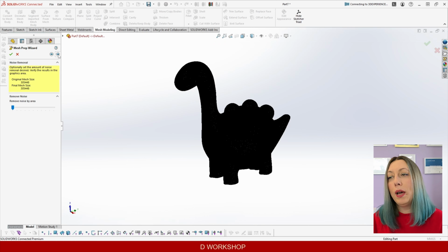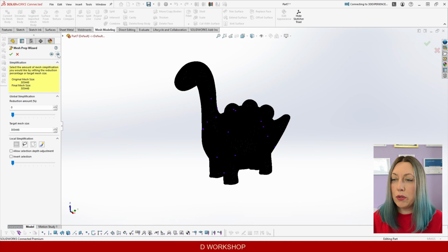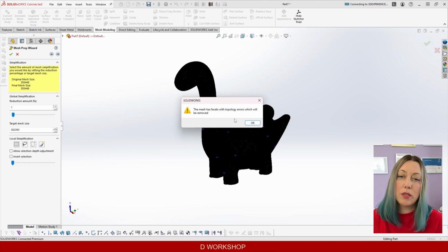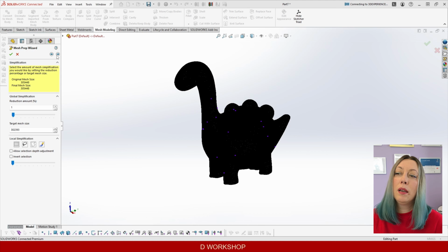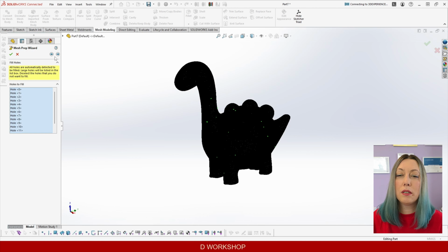And believe me, when this is at a smaller size, it's not possible. What I can give you as advice is that it's really faster if you apply a 1% global simplification. In this case, in 99% of the cases, my mesh is repaired on the first go.